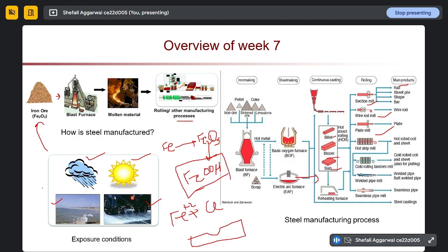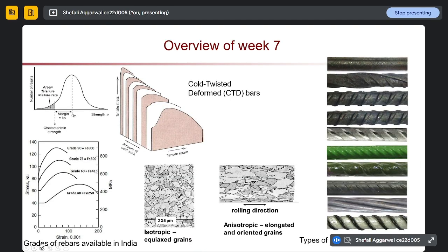carbonation. What is happening in carbonation is that the hydroxides in our concrete will reduce, so the pH level of concrete will drop to 9 to 10. If the pH is reducing, the strong oxide film formed around the rebar will deteriorate and cause corrosion. I think you will read about these things, or might have already read.